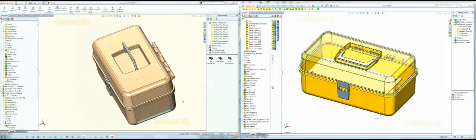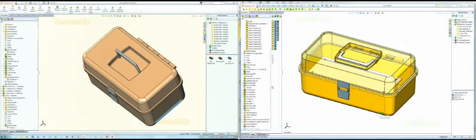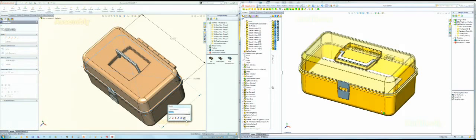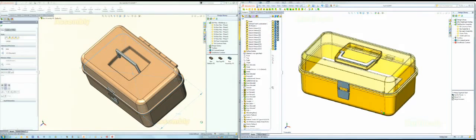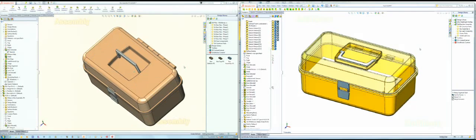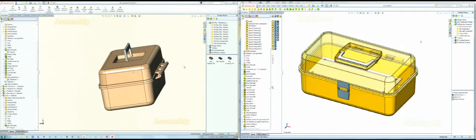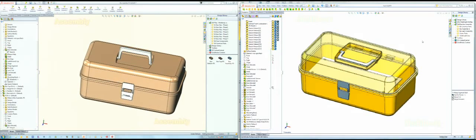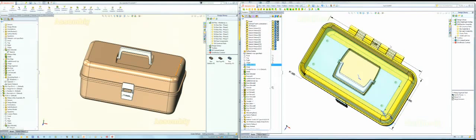And the hinge is still attached, and just for fun, we should also make sure that it goes the other way, even though I really don't want to change this dimension. If I make that 7, just to show that I can, it should change, and the hinge doesn't detach. So parametric design all seems to be in good shape at this point. Okay, and obviously we can do the same thing. We can just double click on these things and they'll both change together.